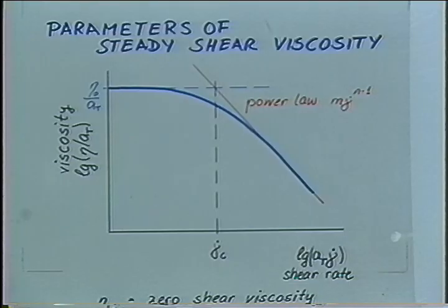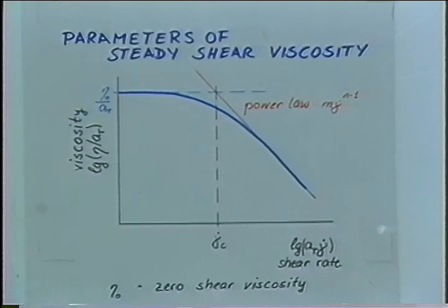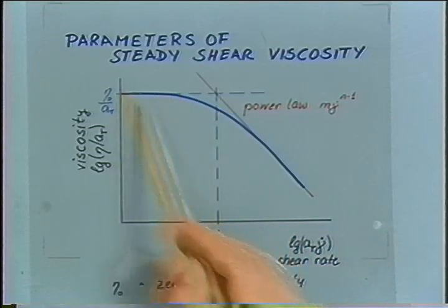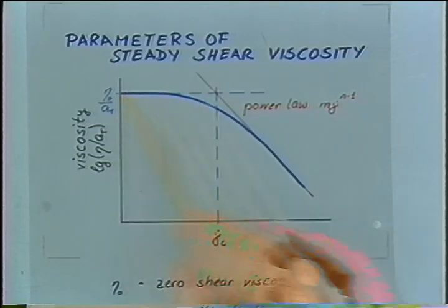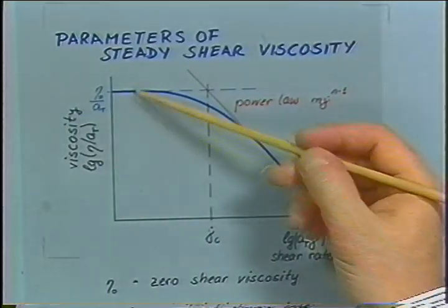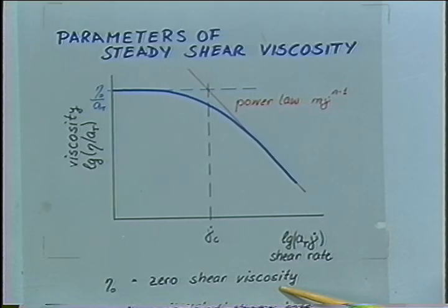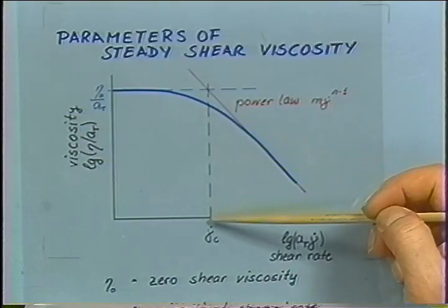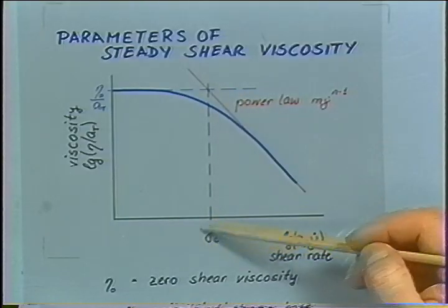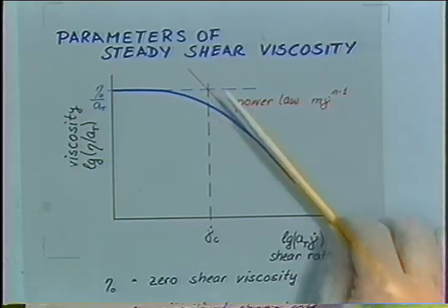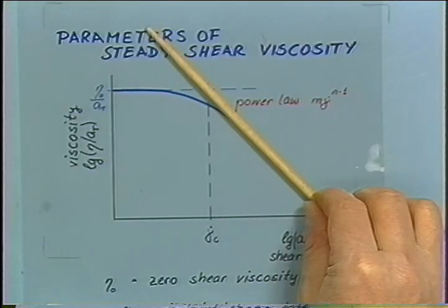The characteristics of that shape now is the following. The viscosity at very low rates is leveling off, and the value is called zero shear viscosity. That's a very important material parameter for our melt. At higher shear rates, beyond some characteristic rate, the viscosity will drop, and it goes down like this, and often is described by some Power-Law behavior as such, and that's so-called shear thinning behavior.